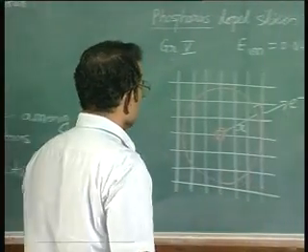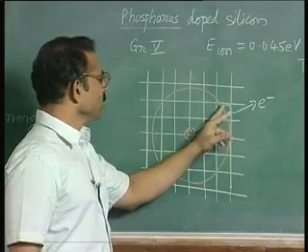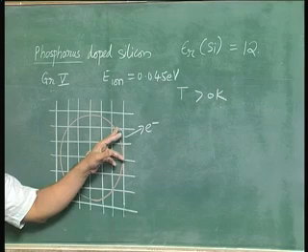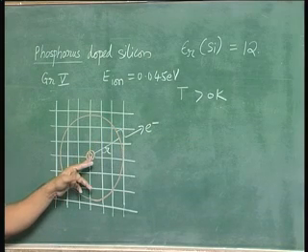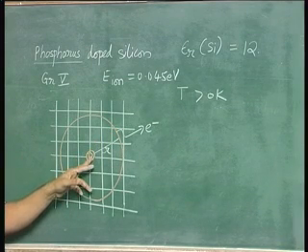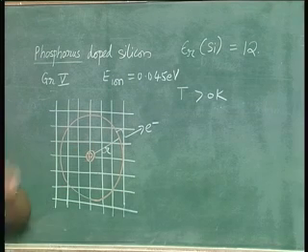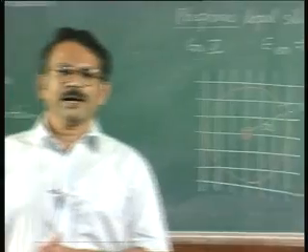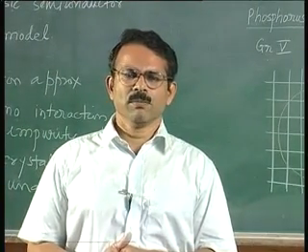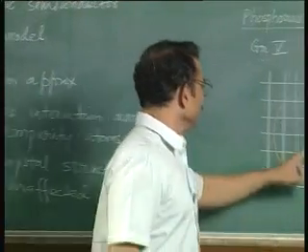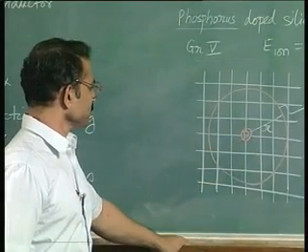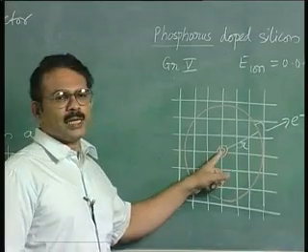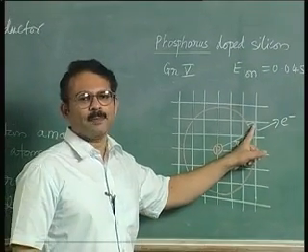Now please note that when an electron becomes free of a phosphorus atom, it becomes available for conduction, but no hole is created. This is because a phosphorus atom without an electron is not a vacancy via which the bonded electrons of the other silicon atoms can participate in conduction. So ionization of the impurity results only in one type of carrier, namely the electrons.